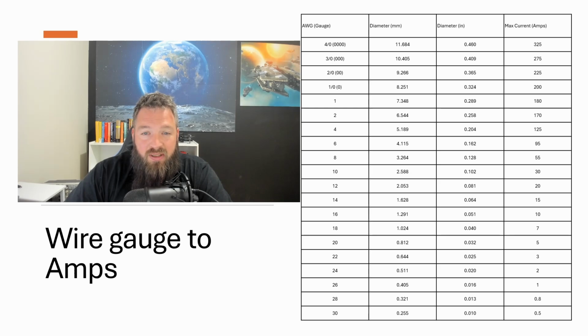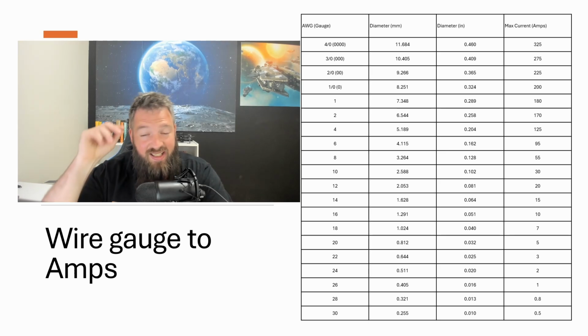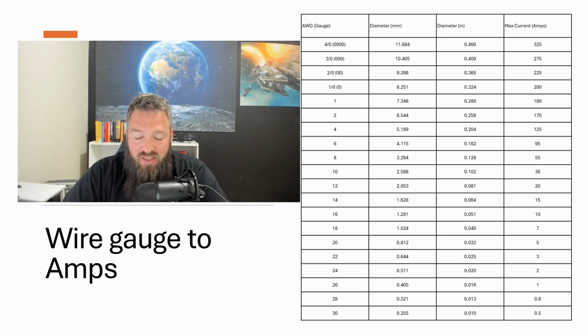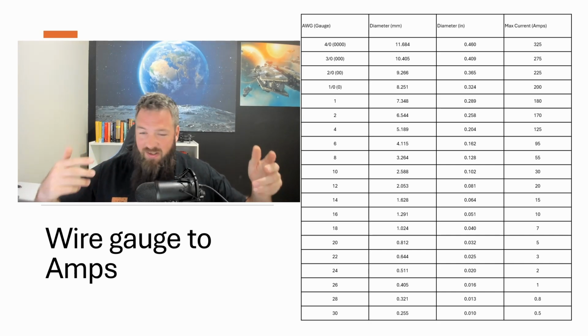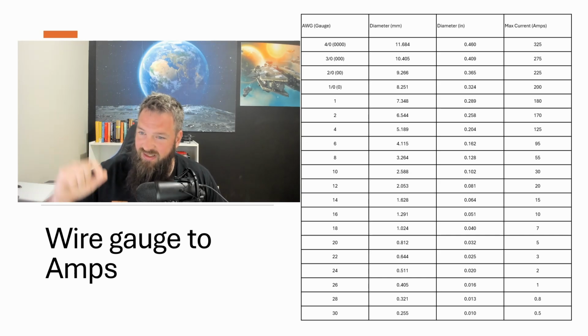So a good example is a 12 AWG wire, where the maximum current that you can put through it is 20 amps. Now this might actually vary depending on manufacturers, so you need to look at what the actual data sheet says this value is. You need to go by what that data sheet says. Why? Because the manufacturers of these wires have to go through various testing to ensure that their wires meet the specifications. So go by that, because there might be slight variations depending on your manufacturer.